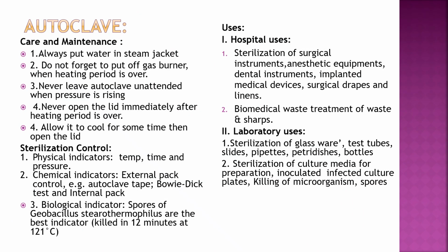The care and maintenance of the autoclave. We have to always put water in the steam jacket. Do not forget to put off the gas burner after the holding period is over. Never leave the autoclave unattended when pressure is rising and never open the lid immediately after the heating period is over. So we have to allow it to cool and then open the lid.